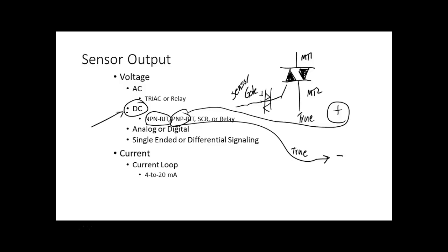It's constantly changing. This Alabama Power is changing polarities every 8.3 milliseconds. So it has no polarity. So when we talk about a common on AC, it's not the negative, it's just a common that we make the measurement relative to. So when we get into DC, we gotta worry about the polarity. So if I'm looking for a minus when it's true, then I'm gonna use a what? An NPN sensor. I know my lines got together up there, guys, I'm sorry.